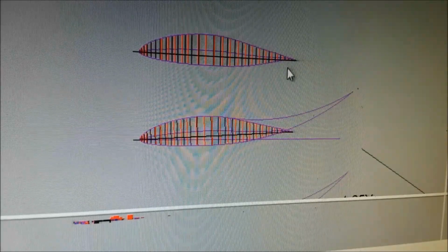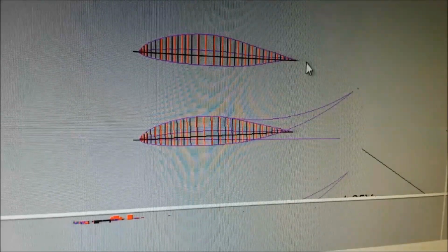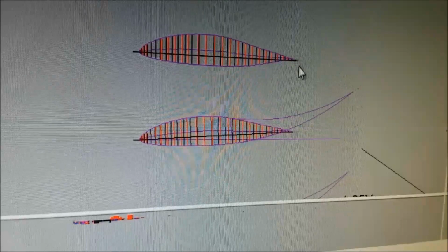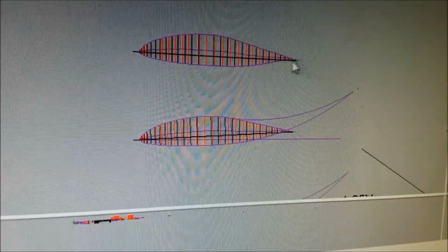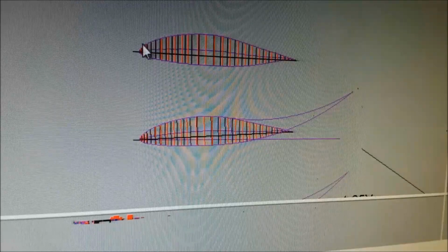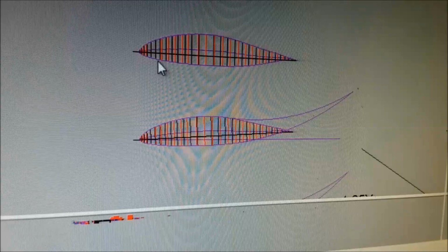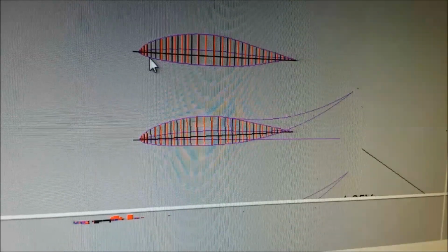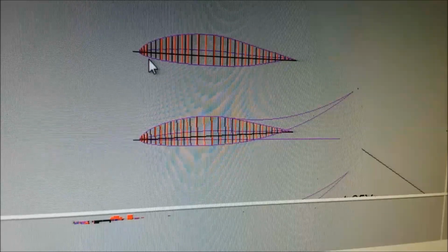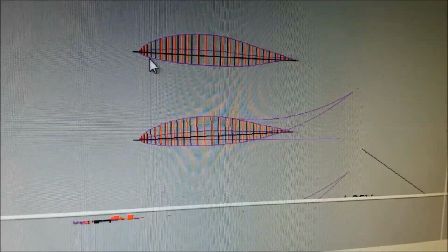Generally, you put a little square block on your pattern so it's not thin there, because it'll heat and burn through. But you cut the top, and then you take your fiberglass, you put about 3 layers over it, and wrap them a little bit more, and a little bit more around the bottom, so they're not all ending in the same place. And you wrap them longer so that little fuzzy ends get held flat, no sharp things sticking up.